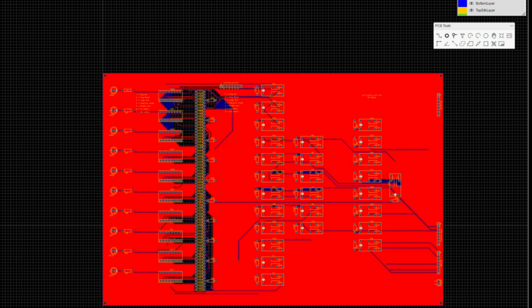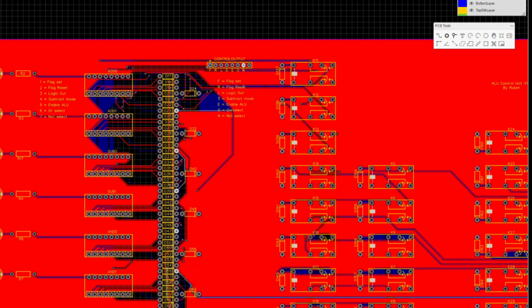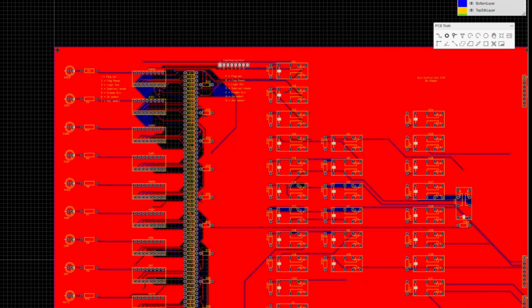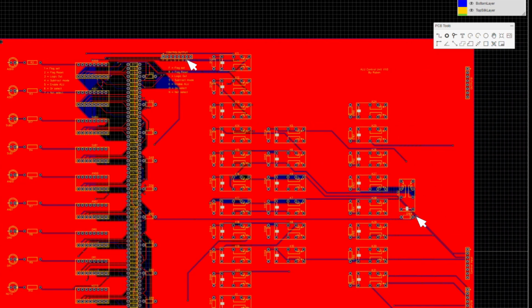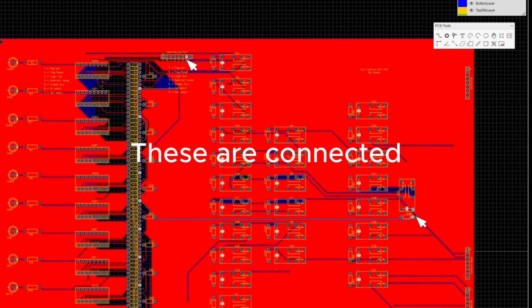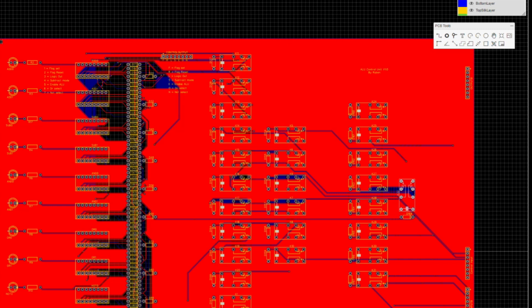So this just gets cut by these, and this basically activates the cut only when it's a NOT operation. As you can see, if I highlight that, you should be able to see this pin here, these ones here light up, which shows you that that's connected up to it, and that activates this relay which cuts the power from the normally closed to normally open, and that's the power that powers these relays. So these turn off, and the power can no longer go to the output.